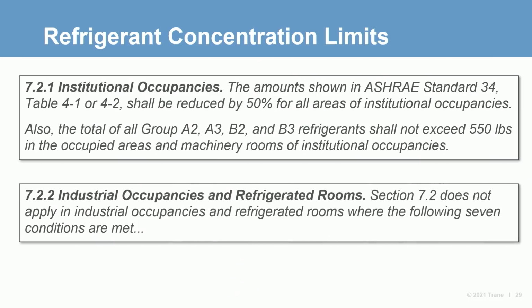The other subsection addresses industrial occupancies and refrigerated rooms. These types of spaces are exempt from the RCL limit as long as they meet a list of special conditions spelled out in this particular section of the standard.